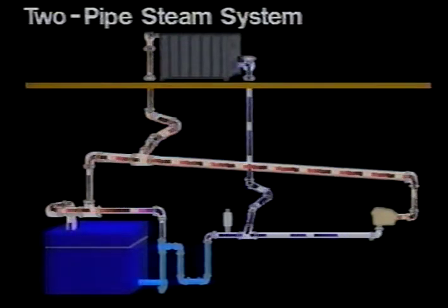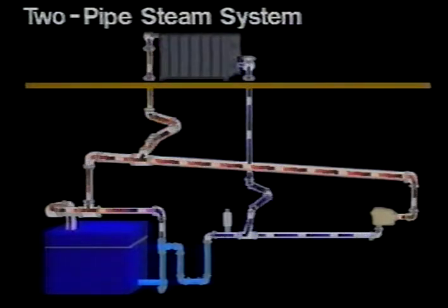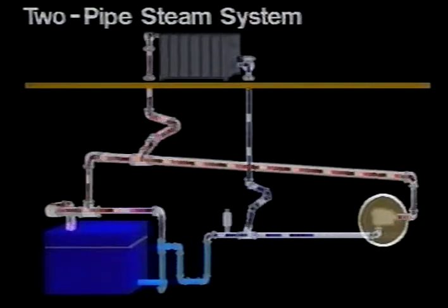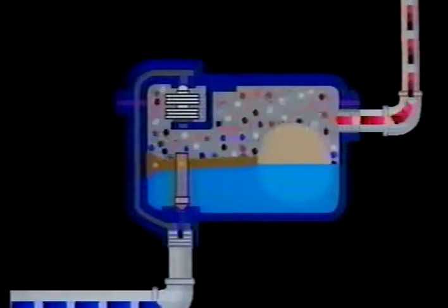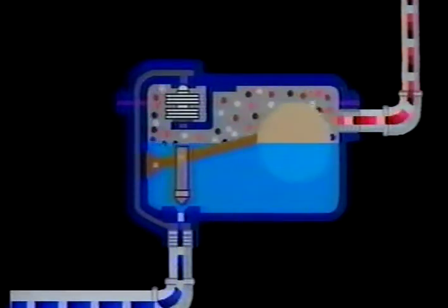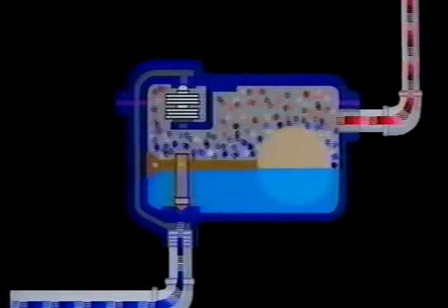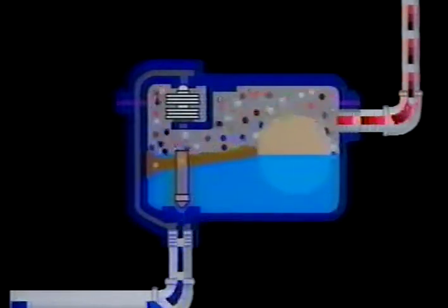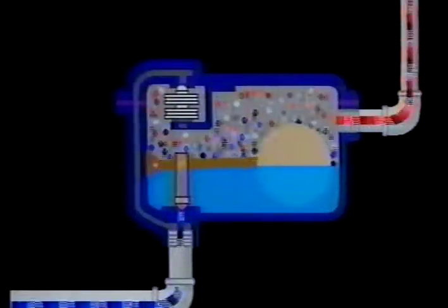Since some condensate does form in the steam supply main, the need to remove this condensate is important to allow the efficient flow of steam through the system. Since thermostatic traps normally wait for the condensate to cool slightly before opening, a float and thermostatic (F&T) trap is installed at the end of the supply main, at its connection to the dry return. F&T traps are fast-acting traps that allow both air and condensate to be discharged from the system main.